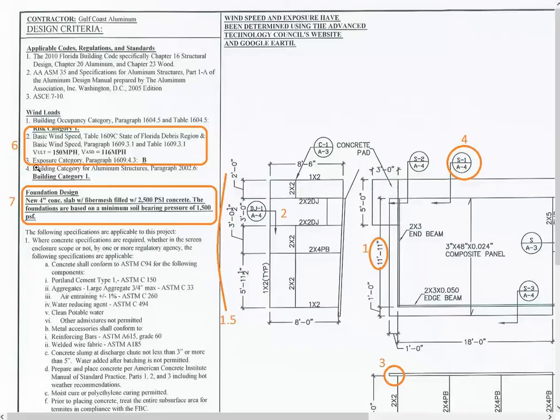And stuff like that. Exposure category represents the amount of distance that the wind has to travel uninterrupted. So once you're inland, this really doesn't matter here. Now, as you get closer towards the sea, where there are big gusts of wind rolling in off the ocean, that's going to get higher.